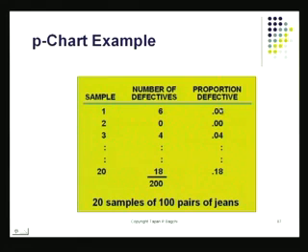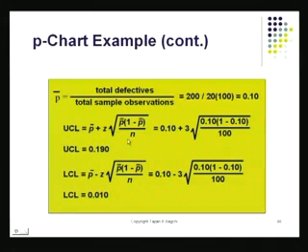That's the size of the lot. So I've got that there. These are my p-values. I'll have to put control limits around these. So for that, I just go to the control limit formula. And the value of z, this time I'm going to be taking a 3 sigma limit. So I put down 3 there. And this is the value of sigma p. And I've got that quantity put down there.